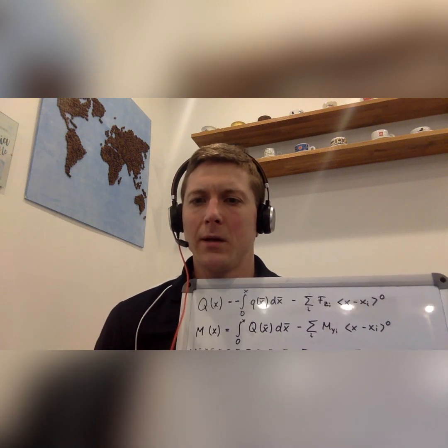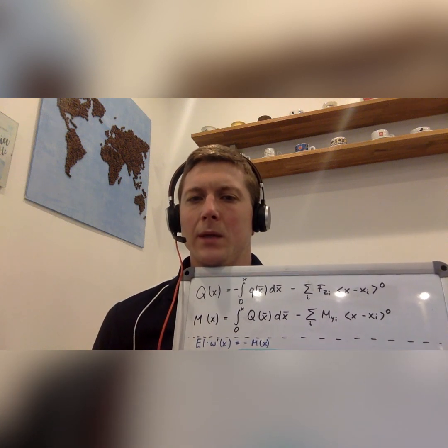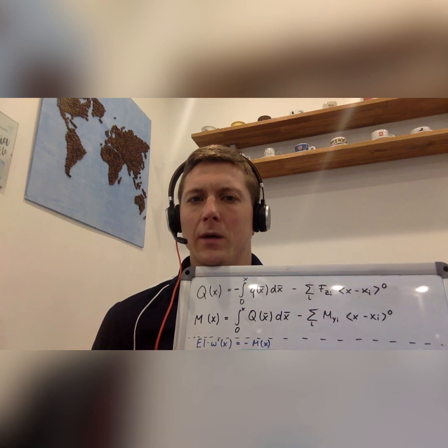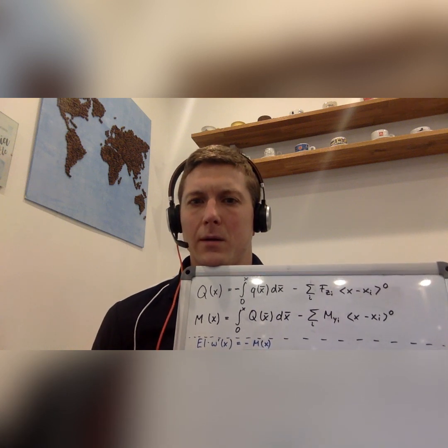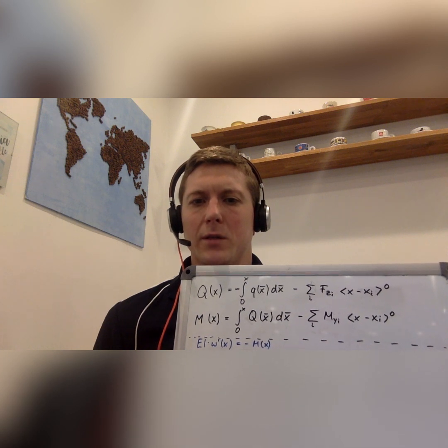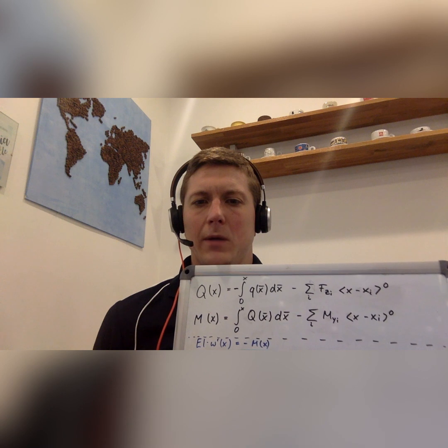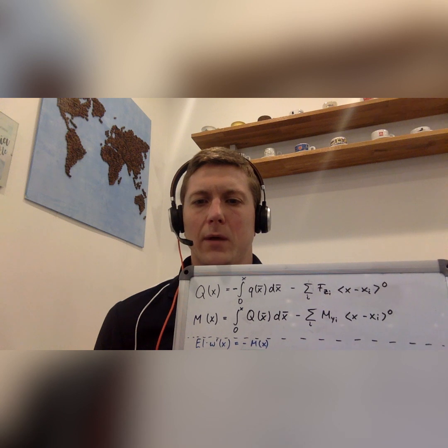So what is the additional equation you could set up? It is given here. There is a relation between the bending moment and the slope of your beam. So not the change of the position itself, but the slope, the change in the deflection line. And if the deflection is called w, then this w prime is just the derivative of w with respect to x, so with respect to the position we're looking at. So the inclination angle is somehow linked to that.